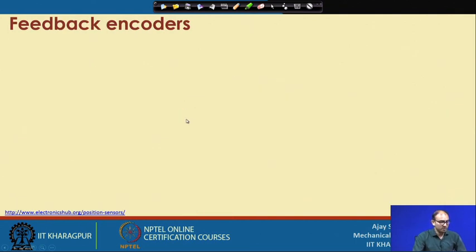So, now coming to the feedback encoders. Till now, whatever we were discussing, every time we have seen that the feedback controller or the feedback encoders play an important role. Whatever the resolution of the feedback controller, you will get a step size of that much only, not because of the system which we are using. We have seen that if you have a linear drive with 0.1 micron resolution, but your feedback drive has 1 micron resolution, then your system will work with 1 micron only.